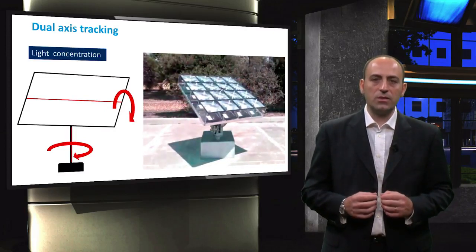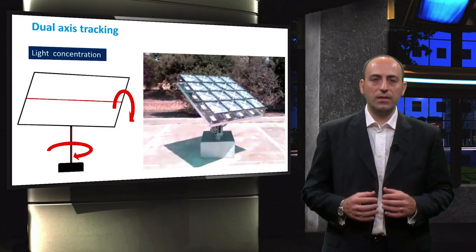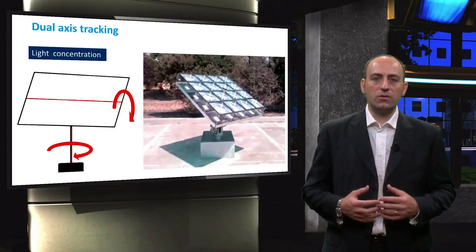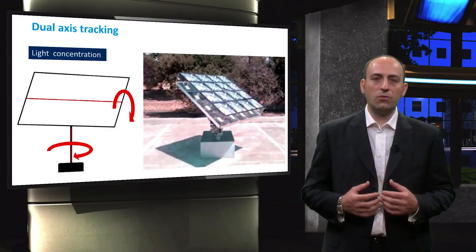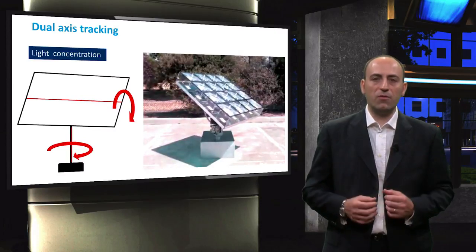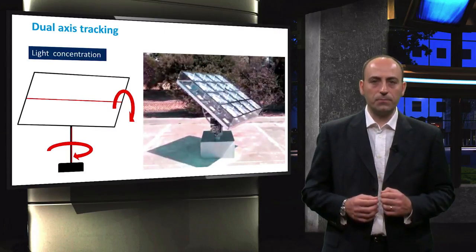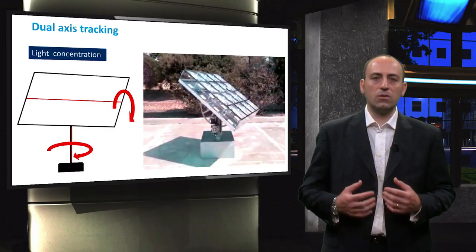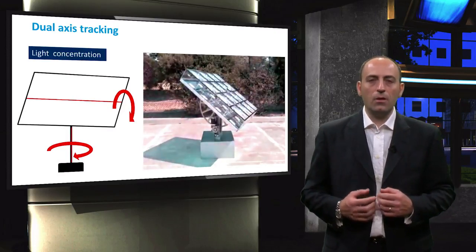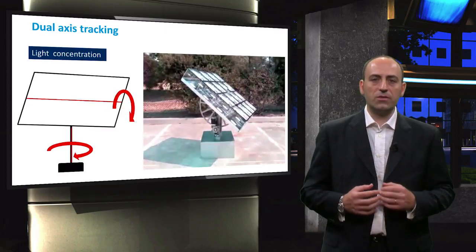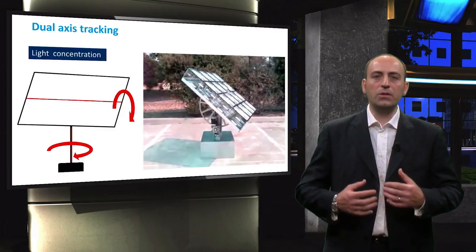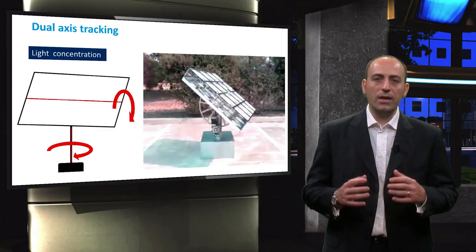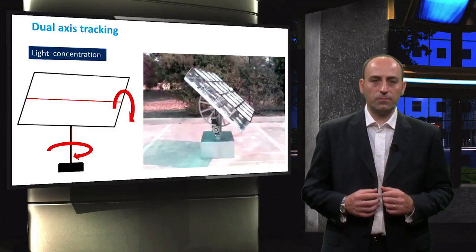This type of solar cell requires high-capacity heat sinks to prevent thermal destruction and to manage temperature-related losses in electrical performance and lifetime expectancy. Therefore, a cooling system is generally implemented in concentrator PV systems. Nowadays, research and development is rapidly improving the competitiveness of concentrating PV in areas of high insolation.